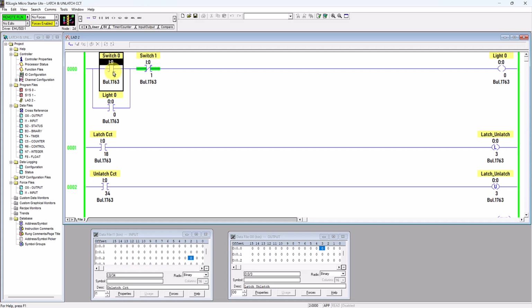Once I click the toggle bit, this will change from normally open to close. The virtual power will flow through the rung to energize the output coil, and this will cause the relevant virtual switch, which is linked to this one, since both of the instructions share the same addressing.